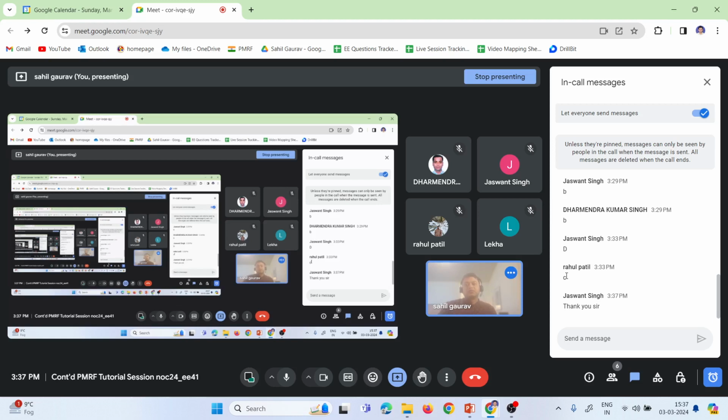You have to just read about the forward backward sweep load flow algorithm, and it is quite easy, not that complex. And we apply this load flow algorithm in radial distribution networks, and radial distribution networks have many advantages, like we have proper coordination and we don't have to invest too much in the protection system.